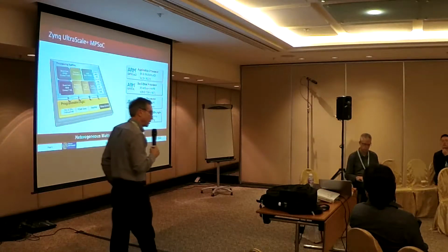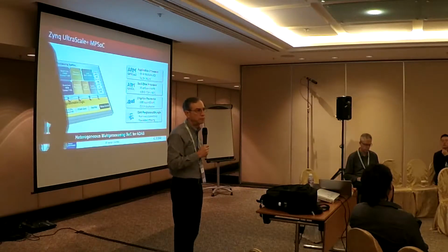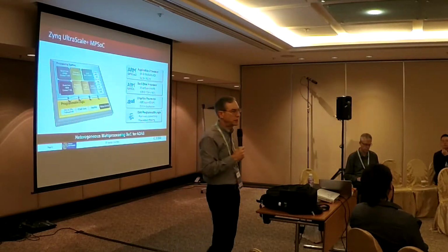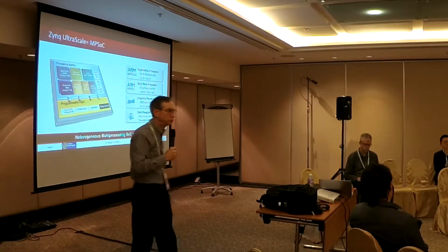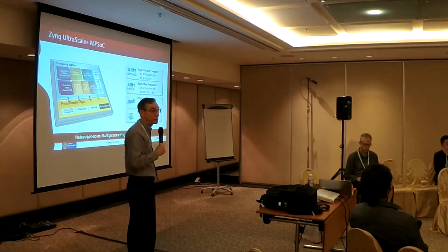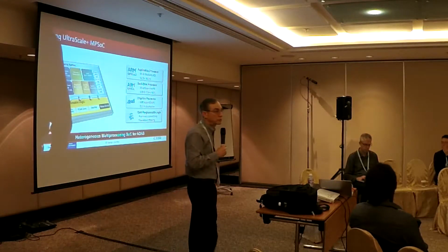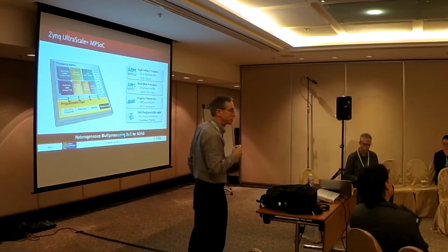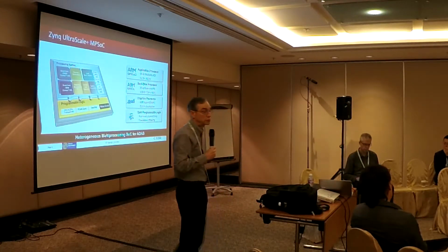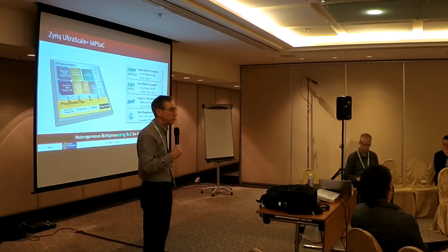Now, for the 3rd processor, there are a couple of possibilities. If the error was simply in the output function of it, it might continue operation, and after that you will resume with all 3 processors providing the same output. Life is good. However, it also could impact the instruction the processor is executing, possibly a jump instruction, in which case it jumps off in the wrong direction and doesn't continue in proper operation.